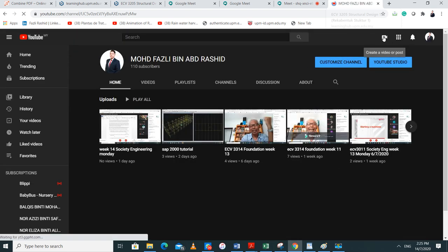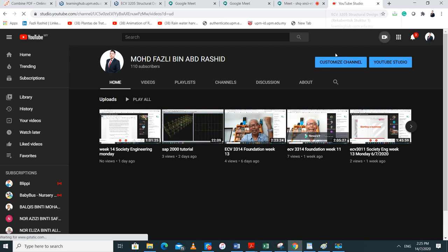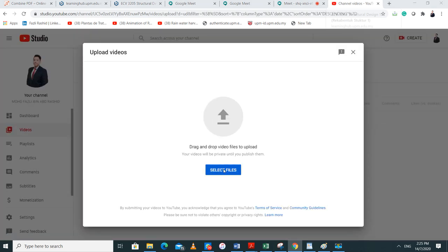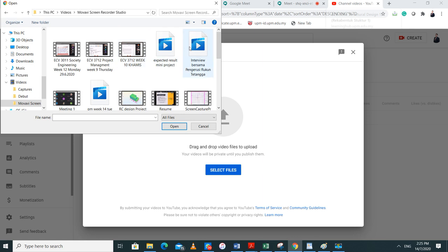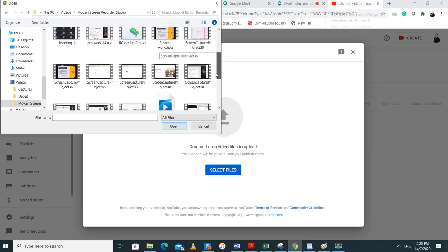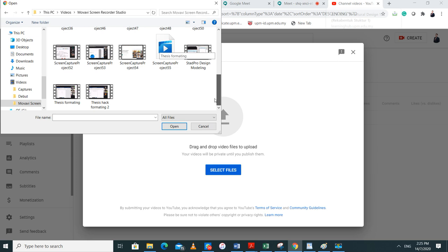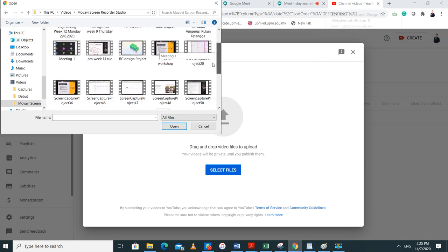Next, on page 15, is the one by Meyerhof. He suggests that there is also a relationship between the ultimate bearing capacity at the tip of the cone and the SPT. In other words, if you do the CPT test with depth, you take the Q sub C at a certain specified depth, and it can also be related to the SPT.